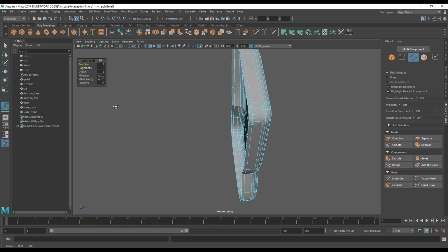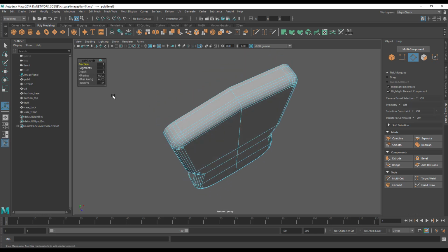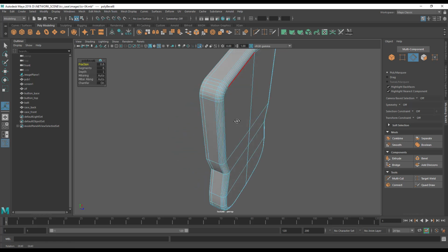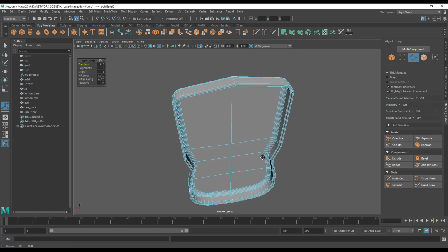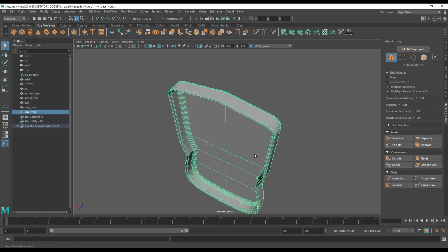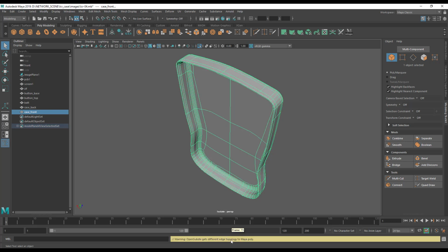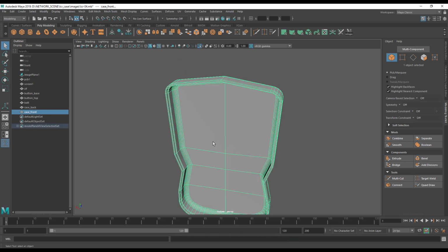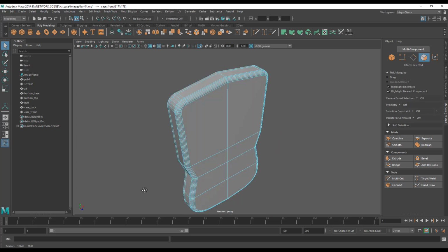We don't want to go too thick, otherwise again we'll end up with having to do some case supports here. So let's see, let's go for about 0.6, slightly bigger bevel on the front, and make sure we've got that internally. Now I'm pretty sure when we smooth this we're going to get an error, same as we did last time. Easy enough to fix, same procedure.